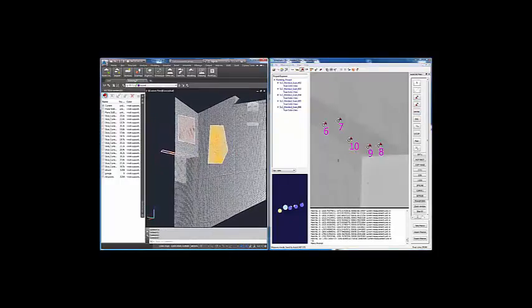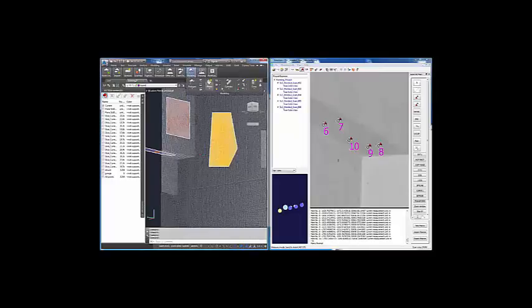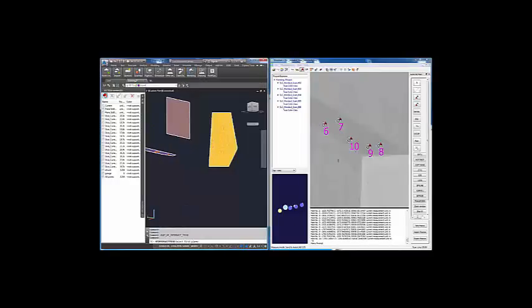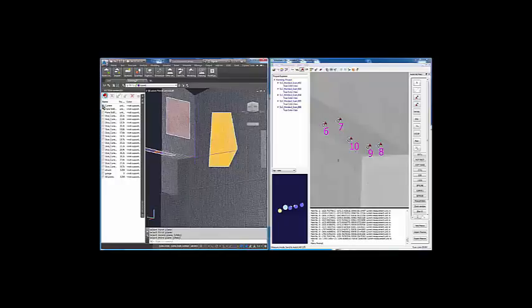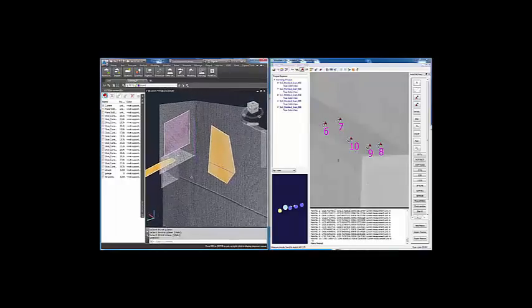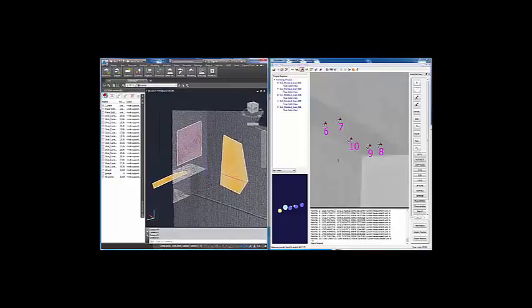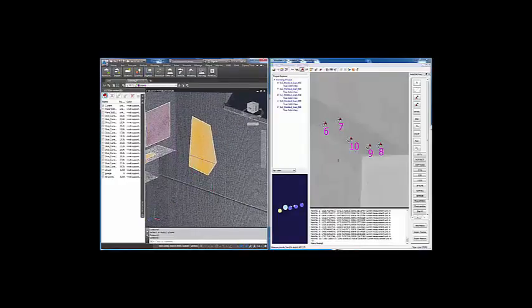Once you have those 3 planes, we can find the intersection lines between them using the intersection tool here, intersection lines or points, and we can just select our 3 planes and get intersection lines between those 3. Additionally, planes can be used to set UCS, so on the digitizing tools panel of the ribbon, just select UCS from plane. And now our XY plane is on that surface, and you can draw panels if you'd like in that direction on that surface.